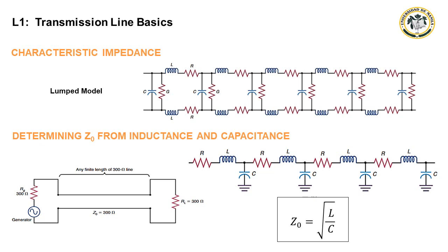In practice, it is unnecessary to make calculations because cable manufacturers always specify impedance. For line lengths of less than 1 wavelength, characteristic impedance does not matter. The common characteristic impedances of coaxial cables are 52, 53.5, 75, 93, and 105 ohms.